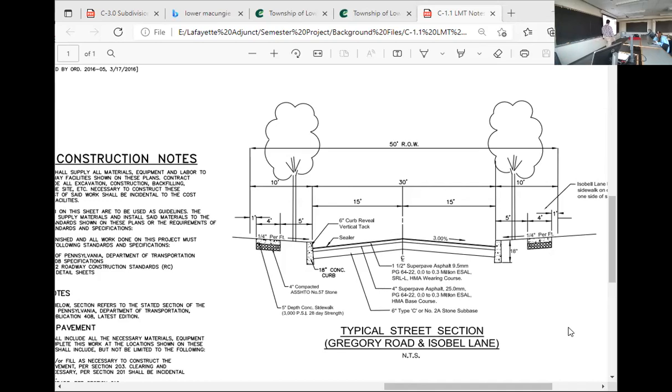Google Drive. So it's kind of like I said, it's kind of like the property line for the street. Okay. It's 50 foot wide, 20 foot, 25 foot for the center line of the street. And then the road itself, the paved area of the road between the curbs is 30 feet, 15 feet on either side of the center.